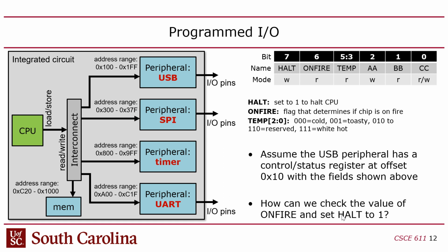So for example, this is an 8-bit one. And by the way, depending on the processor, you may have 32-bit registers or 64-bit registers. This one's 8-bit because this example was derived with the 8-bit Arduino in mind, and it uses 8-bit control and status registers. So this thing's only 8 bits, so the bits are numbered from 7 down to 0,